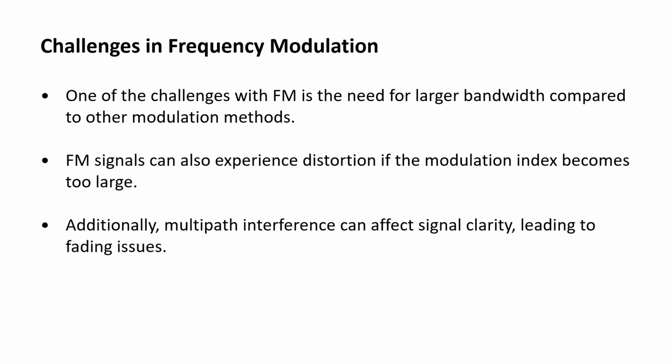Challenges in frequency modulation. One of the challenges with frequency modulation is the need for larger bandwidth compared to other modulation methods. Frequency modulation signals can also experience distortion if the modulation index becomes too large. Additionally, multipath interference can affect signal clarity, leading to fading issues.